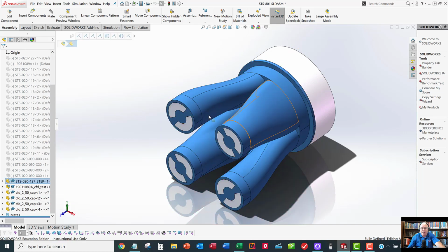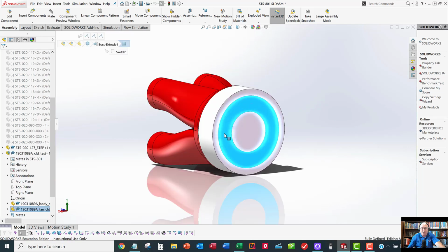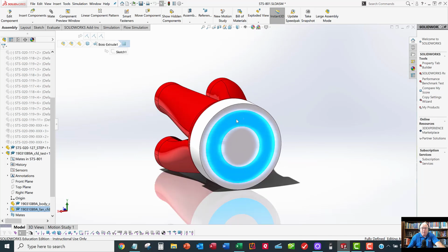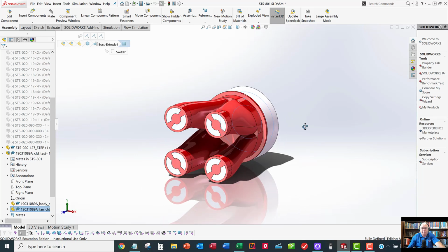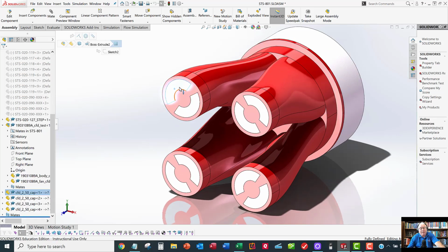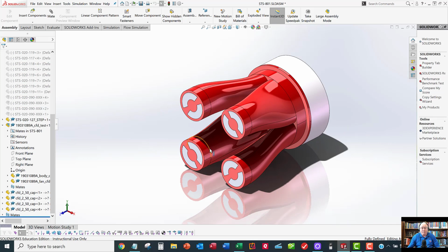And then I simplify the fan to just a couple of pieces. This middle piece represents where the air is coming through, and the inside and outside parts just capture that airflow. We'll use that when we do our flow simulation to define those fan curves we talked about in the previous video. And these plugs are in here not because I want to plug these holes, but because I want to be able to ask for volumetric flow rates coming out of this into this duct, so I use these little plugs to allow me to do that. We'll turn those off before we run the analysis so that the air can come out, but you'll see later when we do our goals what that means.